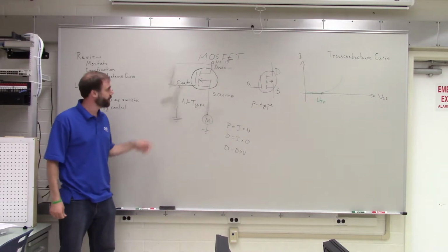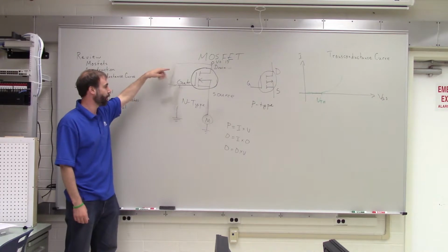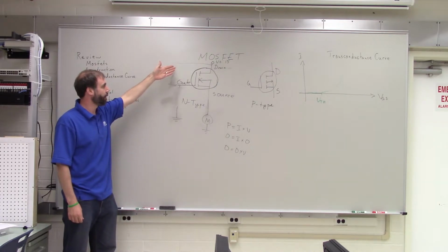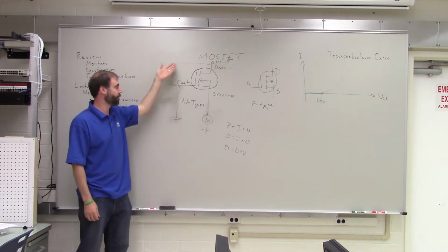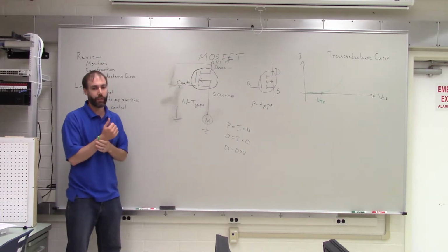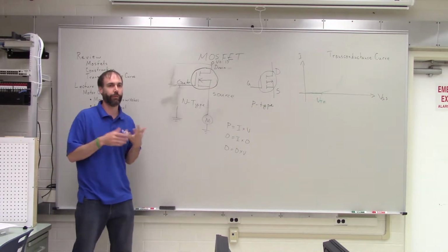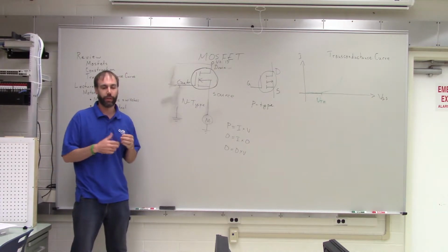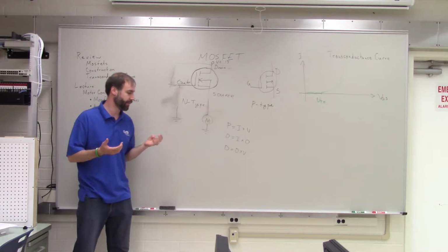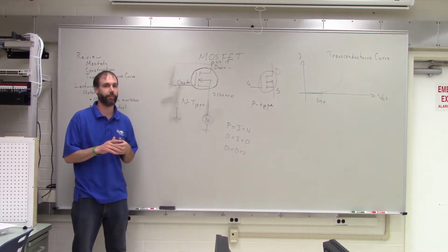So this is all to do with small charges being transferred from either the positive voltage or the ground to the gate through your body. Normally, you would be wearing static discharge equipment if you were handling these types of MOSFETs, because MOSFETs are very sensitive to static electricity, like we discussed last time.